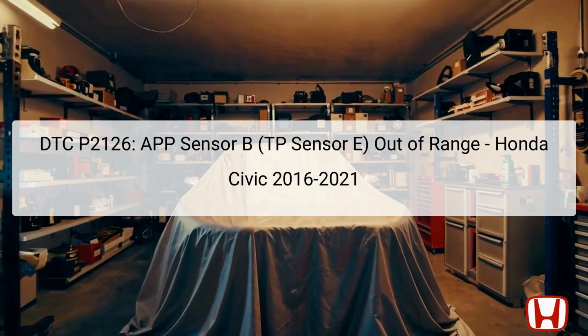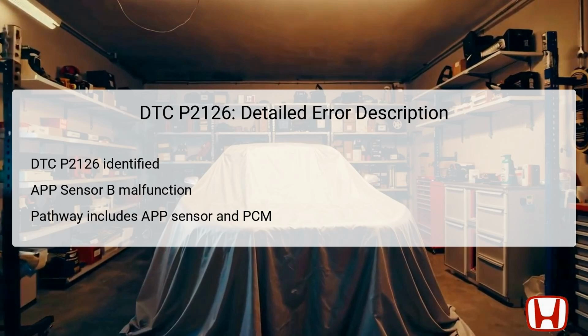the engine management system. The Diagnostic Trouble Code P2126 indicates a malfunction related to the APP sensor B. This error specifically points to the sensor being outside of acceptable operational parameters. The affected components include the APP sensor and the Powertrain Control Module, PCM, which relies on accurate input from the sensor to manage engine performance.